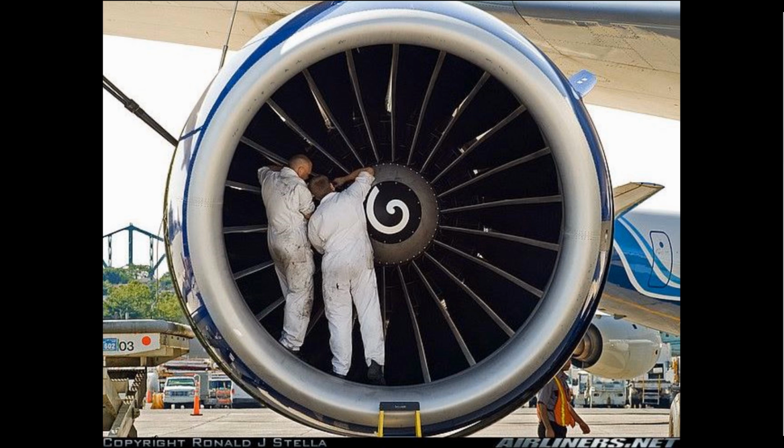I'll go into more detail about design of diffusers in another video, but it's an extremely important component that often gets overlooked because of its apparent simplicity to the untrained eye. I'll be analyzing the diffuser during cruise, which is sometimes called on design because that's where the aircraft spends most of its time. The Boeing 777 cruises at a Mach number of about 0.85. Bad things can happen if the air is still at Mach 0.85 when it reaches the fan, so the goal of the diffuser is to slow down the incoming air to a lower Mach number, somewhere between about 0.4 and 0.7. In my calculations, I'll assume the air is slowed to Mach 0.6.